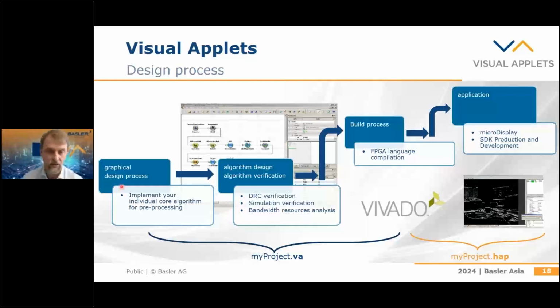So what does such a system look like? You have the camera, the data goes into a frame grabber, into this FPGA. This will perform the pre-processing tasks on the fly, and then the data will end up in the host memory. The applet running in here is completely independent of the CPU or the GPU processing you're doing, but your host memory acts as an interface.